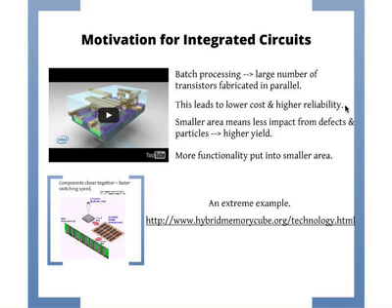The other important point for scaling is that when you make devices small, so in electronics, of course, one would expect that, if you have a junction like this, if you have a big particle that sits on here, schematically drawing, that can short out, right? If you have a conductive particle between these two, then this is no longer a p-n junction. You get shorting between them, and that will not work anymore.